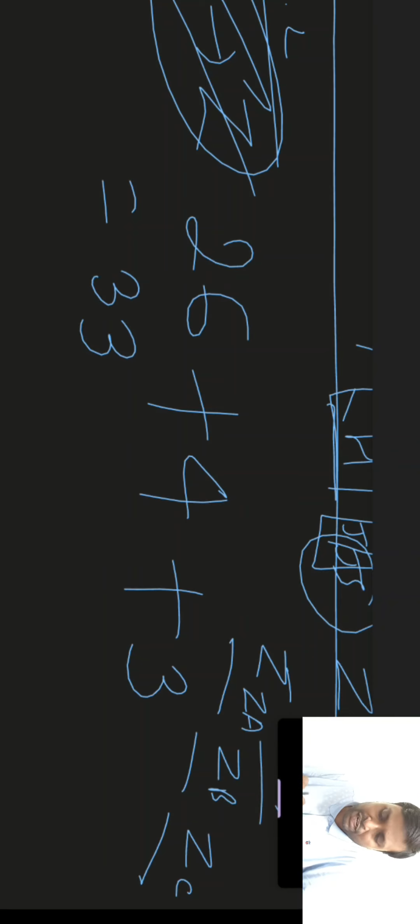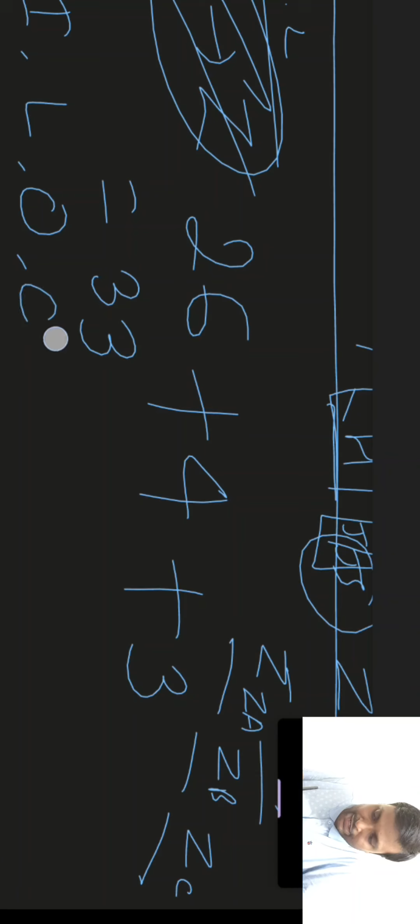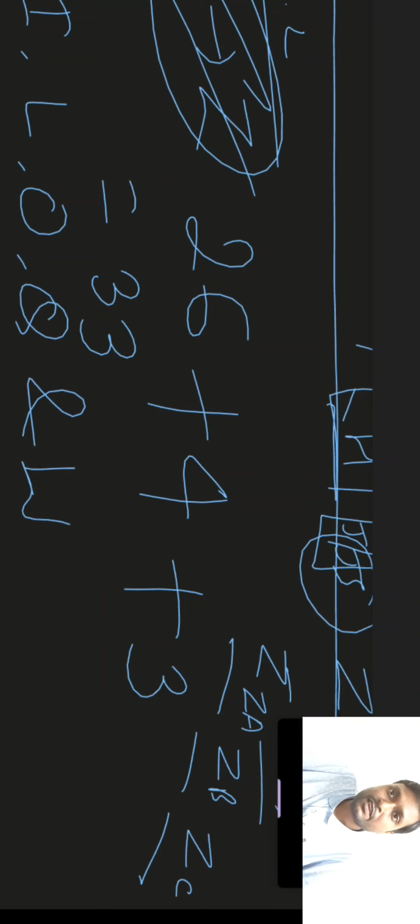Out of these 33, there are some alphabets which are not considered as fundamental deviation. These are I, L, O, Q and W. These letters of the alphabet are not under the fundamental deviation as specified by ISO 286/1988.